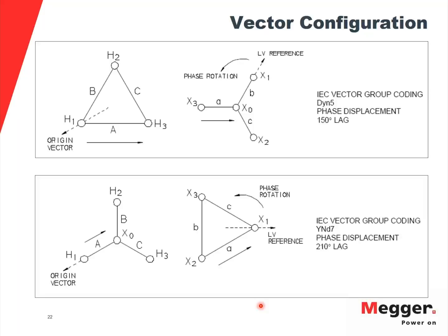That's a good question. Usually when we talk about voltage dependency, it also has a lot to do with the design of the transformer. That 20% or below that I mentioned is what we have observed when we tested a number of different transformers out in the field at different OEMs. So one thing I want to mention is that voltage dependency does not mean that there is a problem with the transformer.